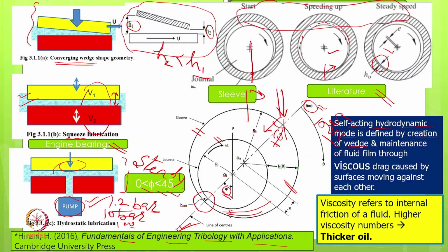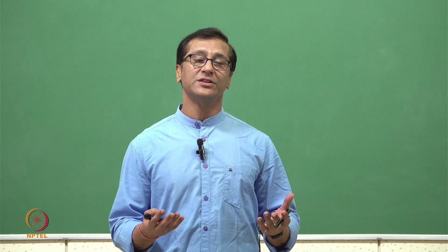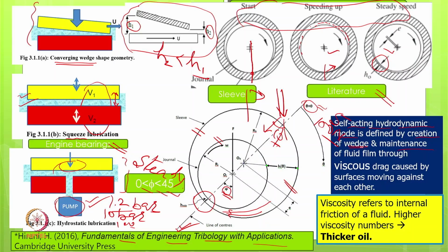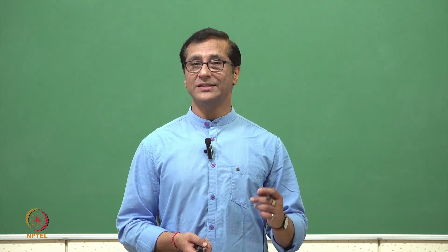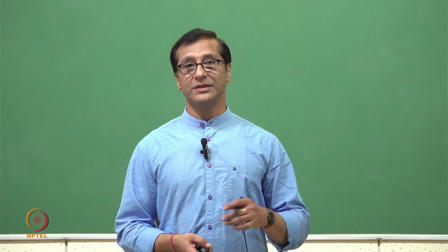So this is very important, that the system really does the necessary thing for sustaining the load. And after generating this wedge action, it is also stable and stabilizing the film thickness, so that it maintains the film thickness, which is important. However, it really requires viscous drag. That's a major thing: it really requires oil viscosity, and we need to think about how oil viscosity really helps to develop a film thickness. That's important to consider.